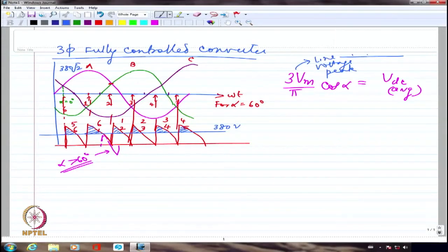So if you have done it and you have calculated the RMS current value, that's fine. Otherwise, if you had calculated VDC average with the complete thing and then minus the battery voltage divided by R as the IDC, I have given still full weightage. No problem. As long as you have calculated IDC like that. And then, of course, whatever is the IDC multiplied by the battery voltage will be roughly the power transferred to the battery.